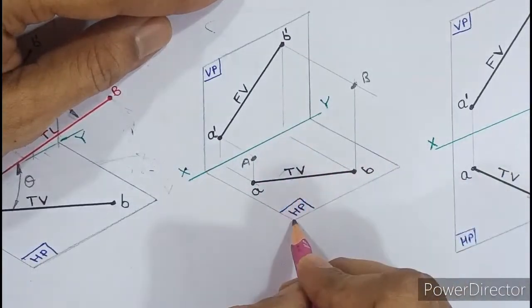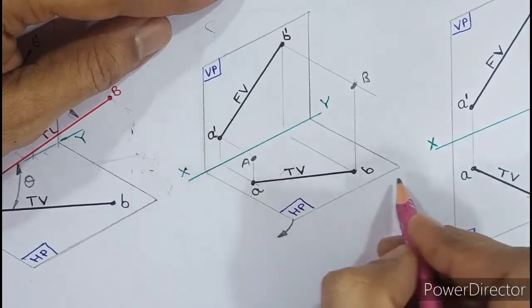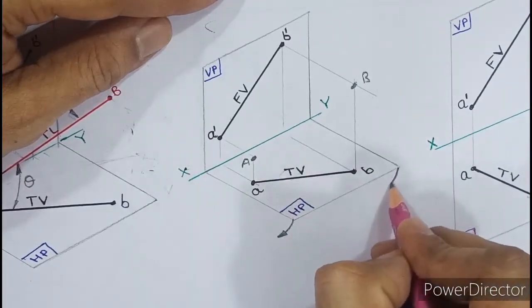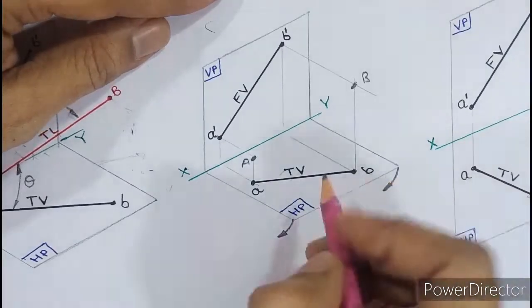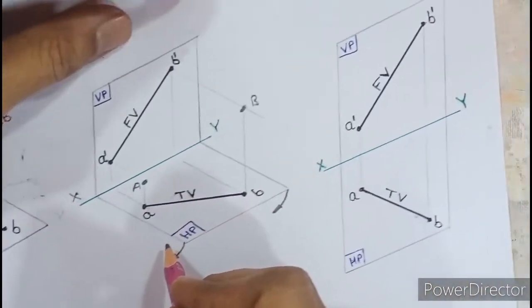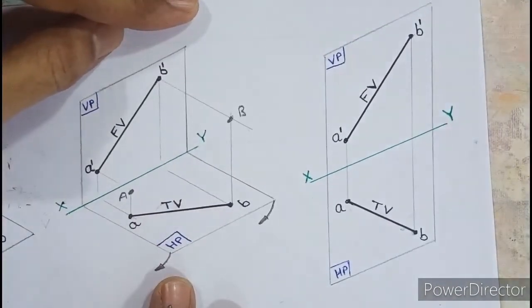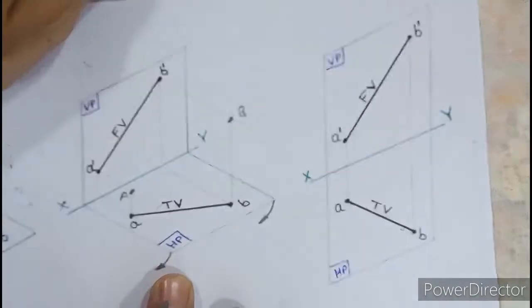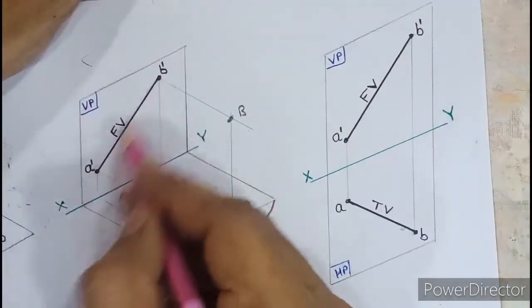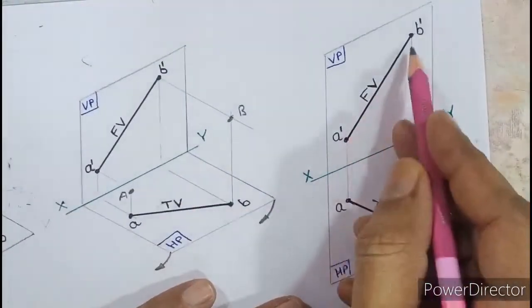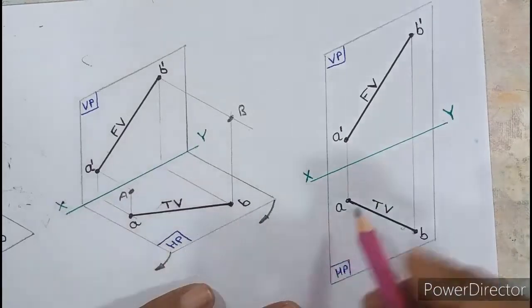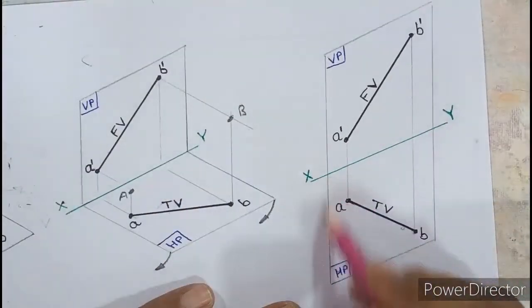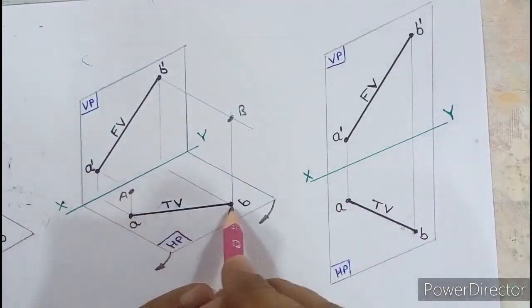We also know that when I rotate HP, when I operate the plane, HP should always be turned in this direction. So carefully observe now, when you turn HP in this direction, this is the diagram you're going to get. So compare both the diagrams. Front view will remain above XY. Now because you have turned HP down, HP will come in the downward direction, isn't it? And along with HP, top view will also come down.